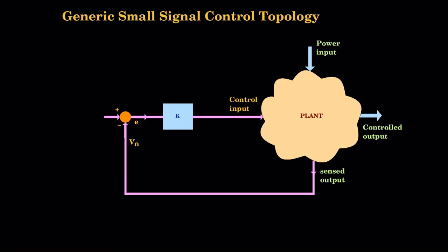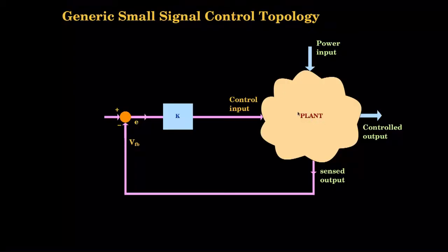If it is a multiple input, multiple output, it will be multiple gains. If I am having 3 states in this plant, it's a third order plant, 3 states, then this will be 3 gains. So, what is meant by full state control? All the states are fed back.